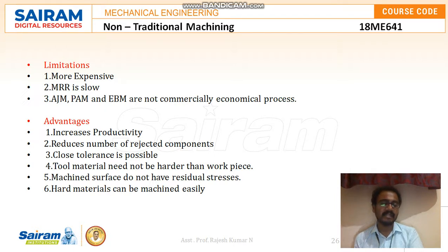Based on that, some error, that is 0.001%, I can say. And the tool material need not be harder than the workpiece, which is a very important aspect to be noted in the conventional machining process. But here that is not the case. Moreover, here the tool is not at all touching the workpiece, so we need not worry whether it should be harder or sharper, or whether it's an expensive tool. All those things don't matter here at all.